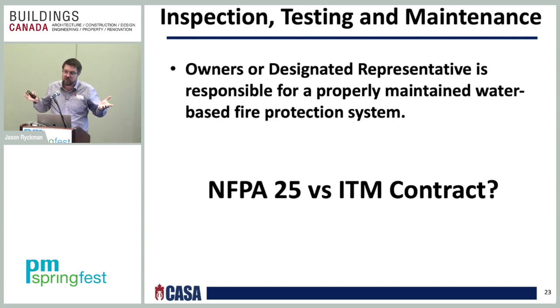If they want to check their dry systems, make sure that the inspection reflects that contract, that you only do the dry sprinkler systems on that water-based fire protection system. One of the main contracts that you'll see out there is one-year annuals. If you do an annual, you have to follow everything for your annual inspections. It has to marry with the contract and the inspection forms.